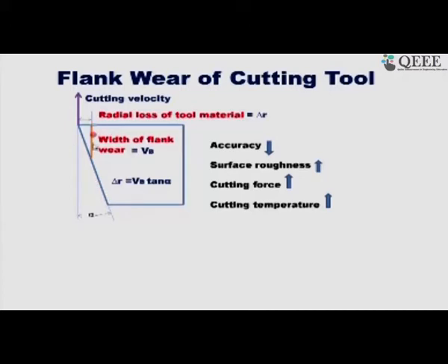Over this there is no clearance, and that will lead to increase of force, temperature, rubbing and so many things, which will finally spoil your job. Why? Because the surface of the flank is not smooth, force will be too much, temperature will be high, and temperature is also damaging: residual stress, then dimensional deviation, oxidation, burning, lot of things are there.